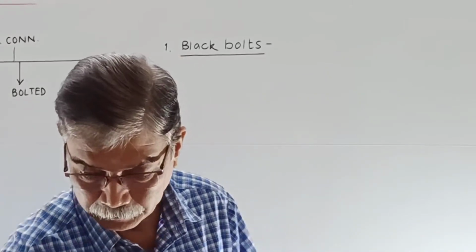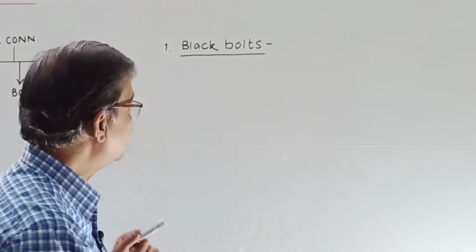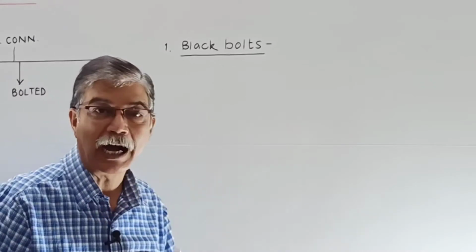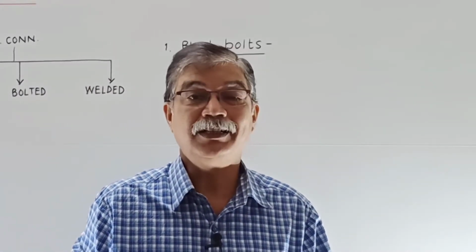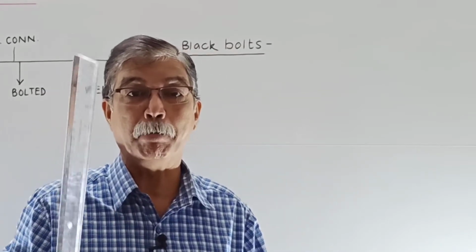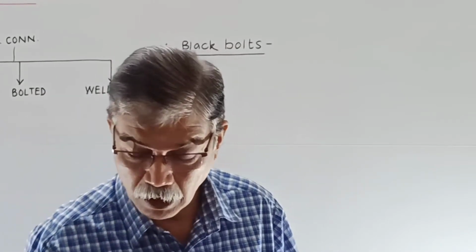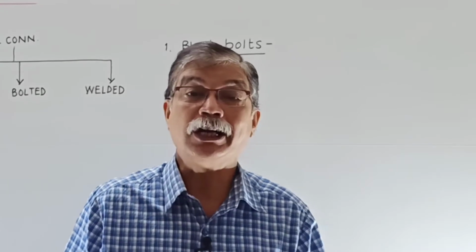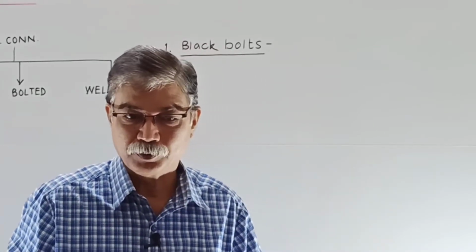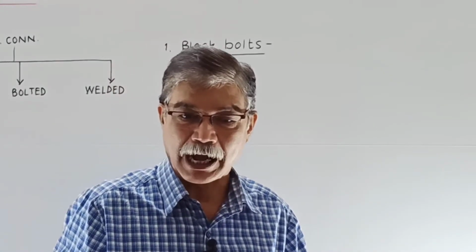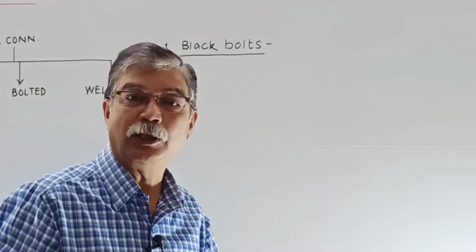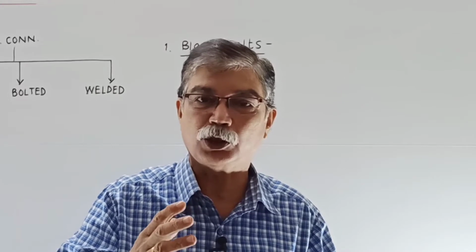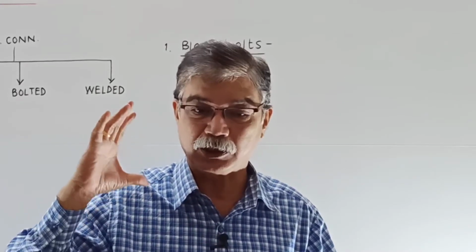Most important thing, these black bolts are not recommended for the connections subjected to impact or fatigue or dynamic loads. So black bolts are not recommended for the members subjected to impact, members subjected to fatigue, members subjected to dynamic loads.